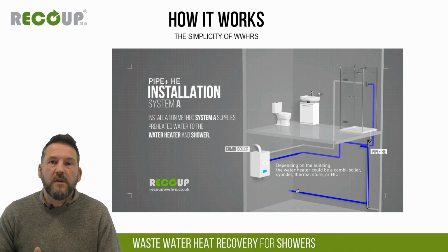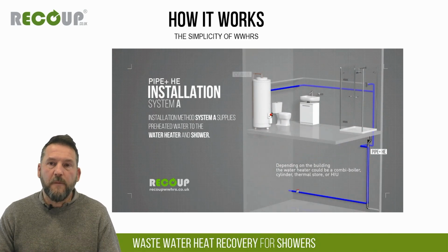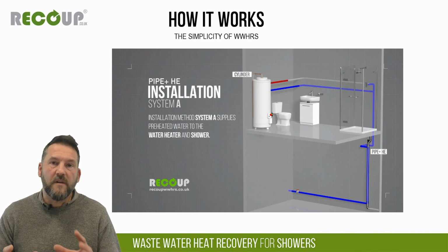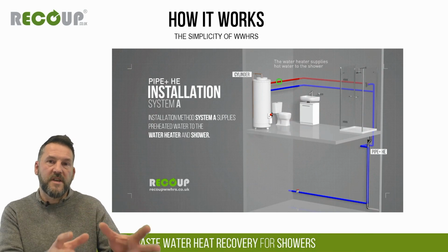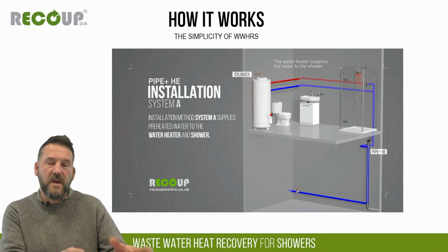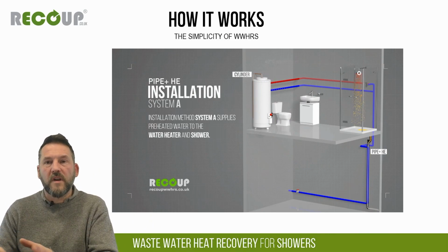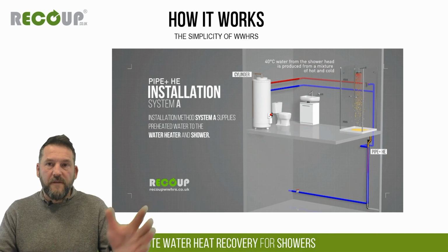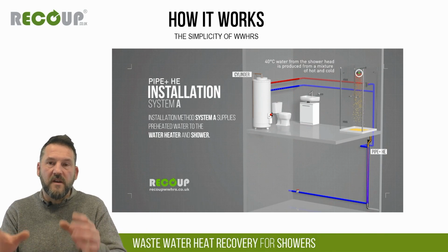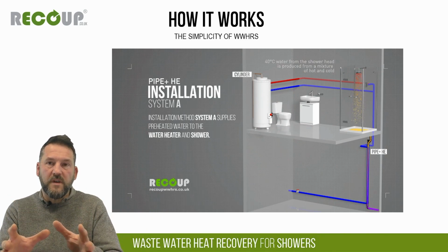Now, when you shower normally without wastewater heat recovery, with a thermostatic mixer, that comfortable 40-41 degrees that you're getting out the shower head is produced by around 50% generated hot water, about 55-60 degrees, and around 50% incoming cold water main at around 10 or 12 degrees. And that 50-50 mix at the shower mixer gives that comfortable 40-41 degrees.